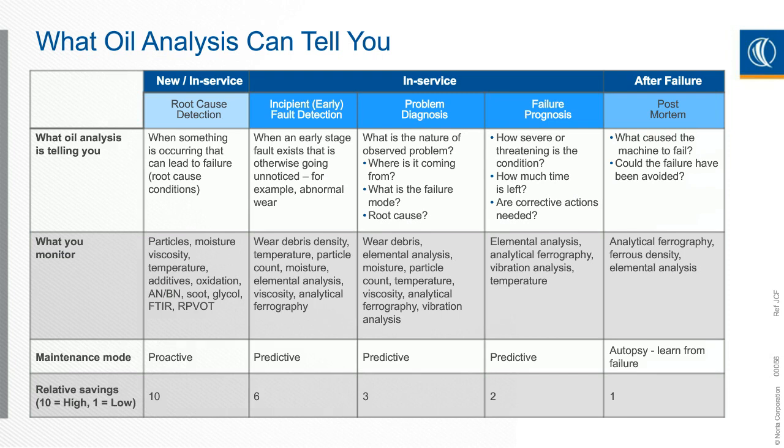Most likely you're going to have some level of wear debris or some level of changes in the oil that's in there from what you had previously in that machine. So all that information can tell you what happened, why that machine failed, what that failure was, and whether you can avoid it in the future. This is very important. Obviously, the relative savings at this point for that particular machine is not going to be that high, but it's going to help prevent that potential failure in the future. So this is also very important.